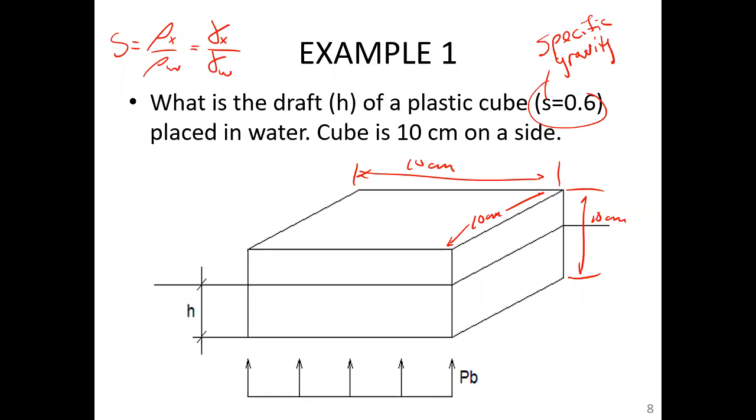Because they displace more volume of water than they weigh. So again, if a ship was collapsed into one ball or cube, it would definitely sink. But because we form it into a shape that displaces much more water volume, and therefore weight, than the weight of the ship, it floats. So we are basically asking, what is the draft of this system?